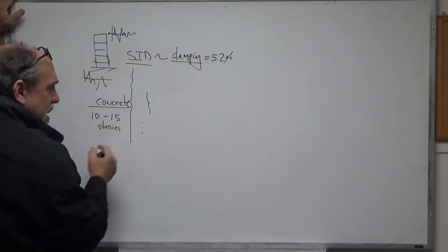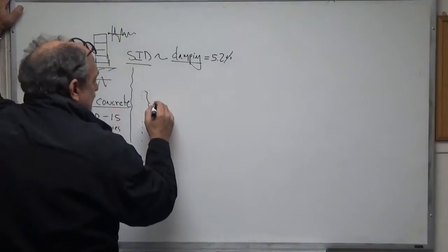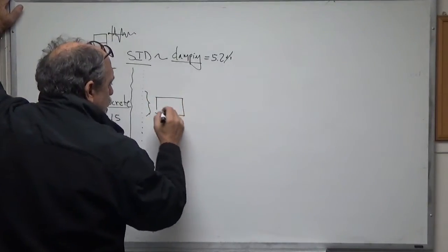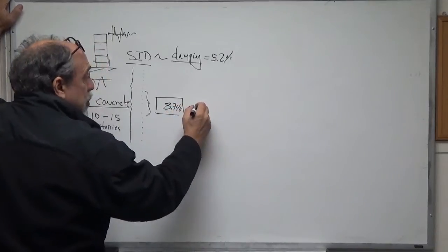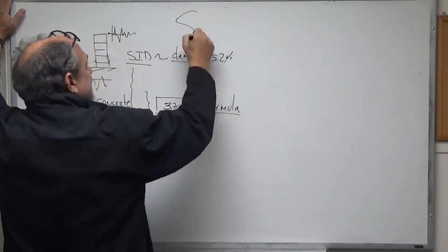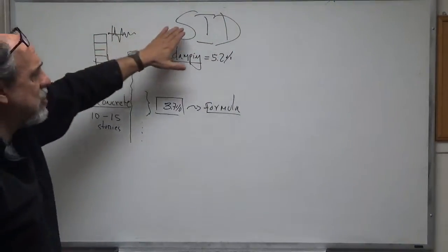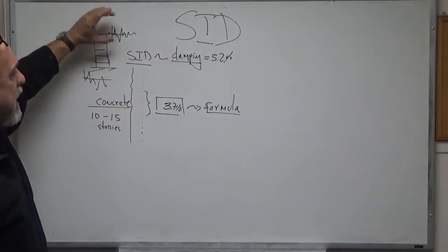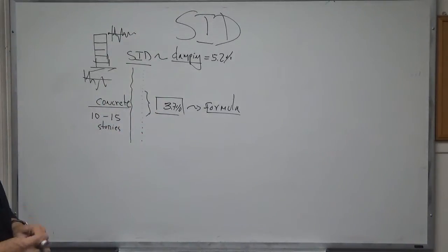The point is not to describe the research, but that you could say that we recommend this number, 3.7% damping, or this formula, or something. The point here is that system ID is the key, because it's with system identification that you've been able to convert the measurement of the sensors to the quantities that you're interested in. Okay?